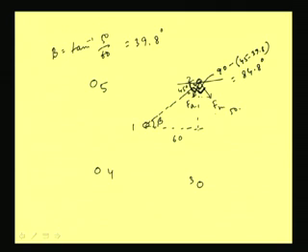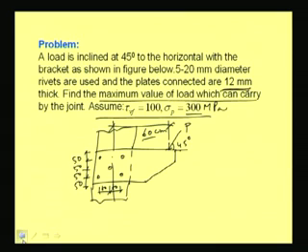So, now what else I have to find out? F_A and F_M. To find out F_A and F_M, before that, I have to find out what is the distance. See, this is an inclined load. So, either we have to make two components, one vertical and another horizontal, in this way we can calculate. Otherwise, let us find out the perpendicular distance between the CG and the load. So, this we can call E.